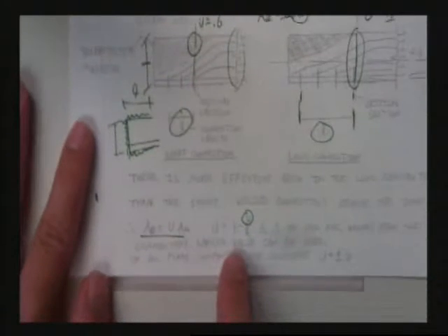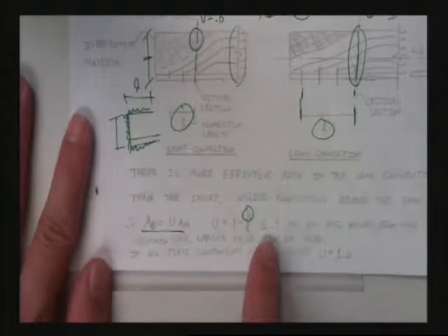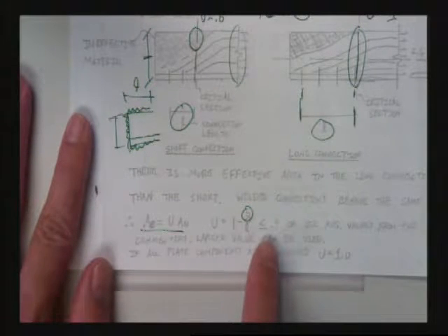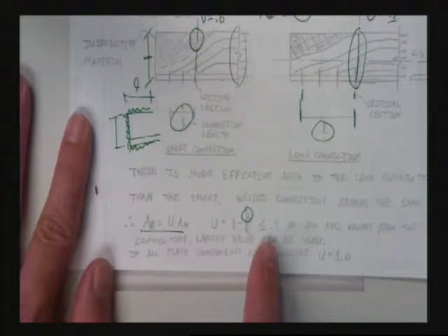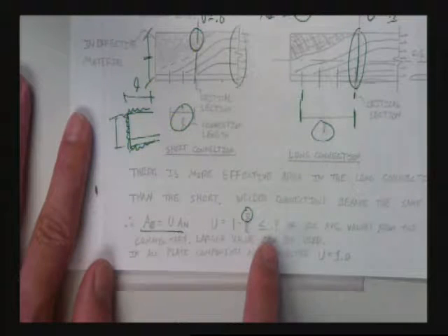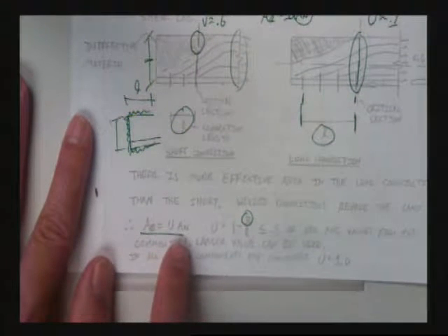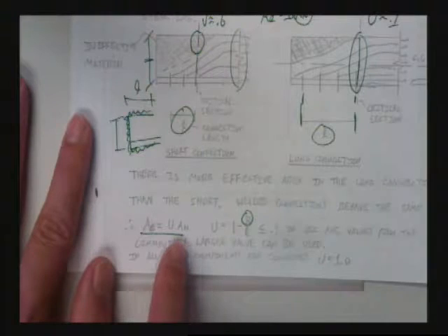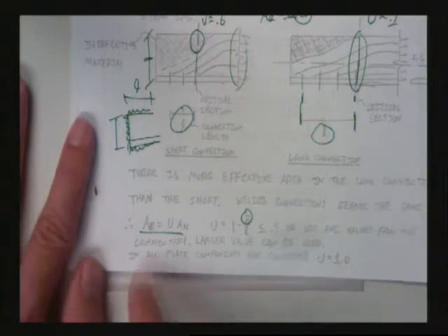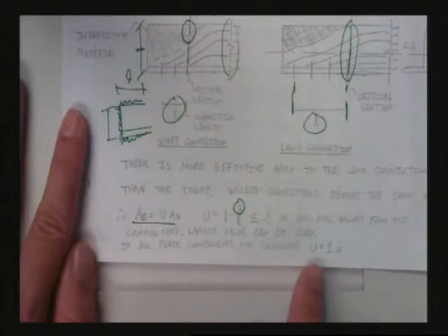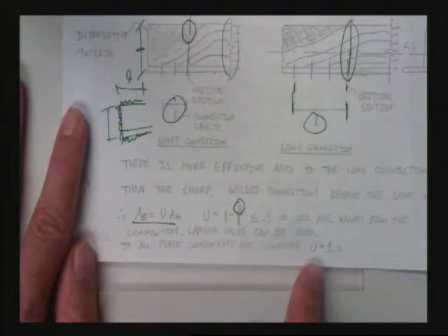So we're going to use 1 minus x bar over L. It has to be less than or equal to 0.9. So if you have an outstanding leg, the most U you can have, the highest U that's possible is 0.9. What does U do? What is it all about? It's reducing your net area, isn't it? It's reducing your net area. Now, if all your plates are connected, you can use a U of 1. Okay? Okay.